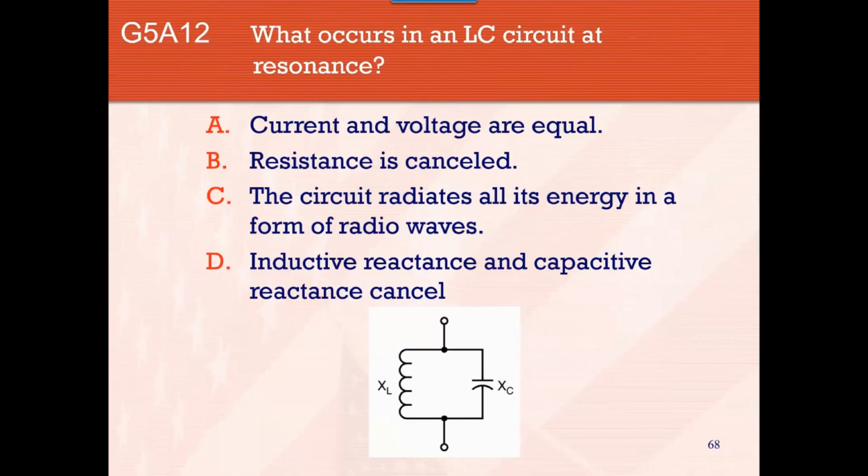So if I have a +1 on one and a -1 on the other, they, just like in algebra, would cancel each other out. So if I had current flowing through this tank circuit at resonance, then there's basically 0 resistance going through that circuit. The only resistance that would be there would be whatever residual resistance is there by the fact that this is a coil of wire, some very minuscule resistance.